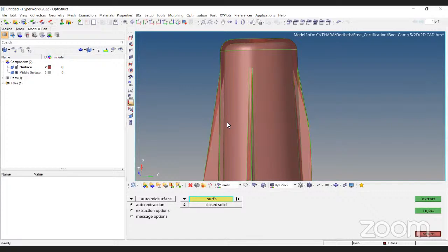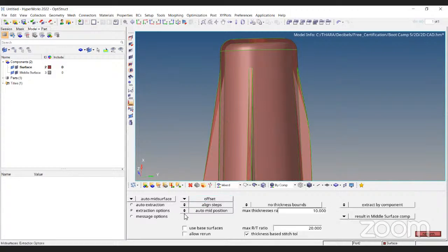And you can ask me, first we are only going to extract the mid surface, so why are three options available? These options will work based on the geometry of the component. See, in a car, all the components are not flat, and all the components are not curved. Many of the components may not contain any bolt beads or fillets.